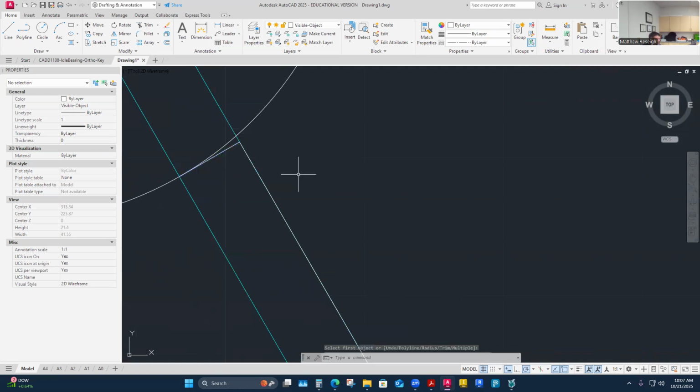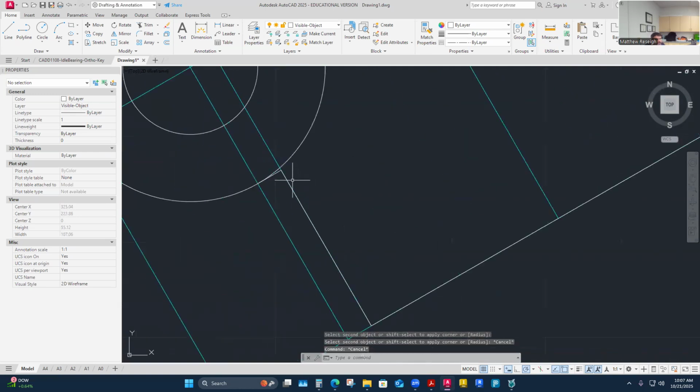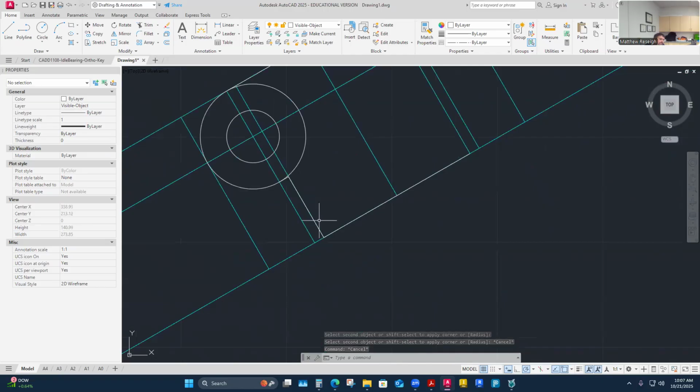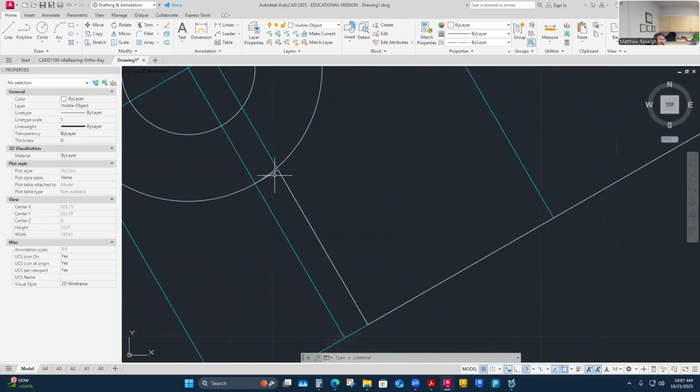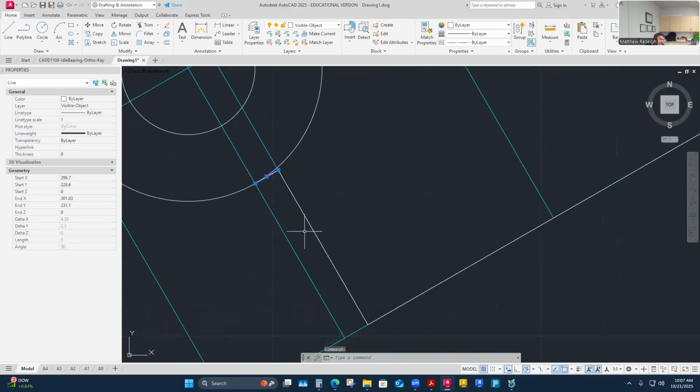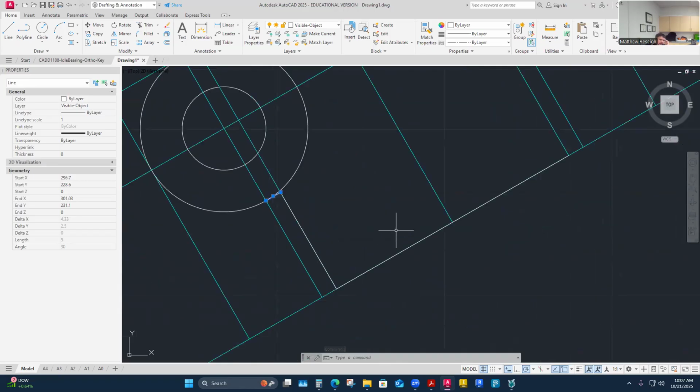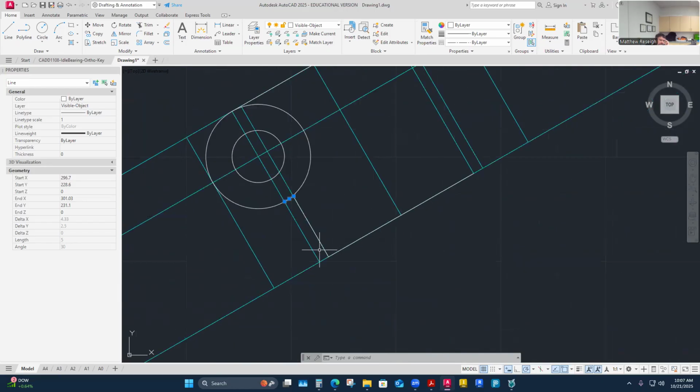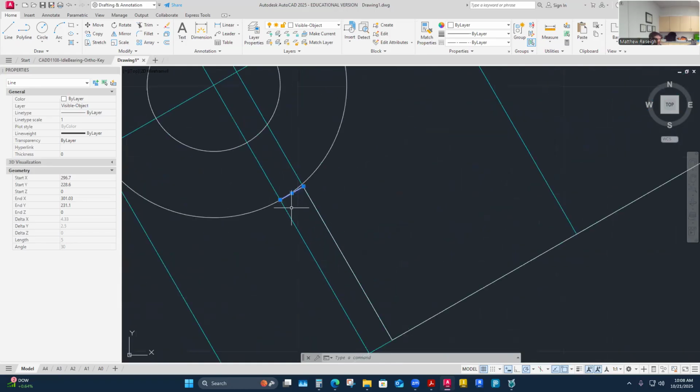And it won't let me do it because of the distance I have, which is what distance? Right here. It's only 5 millimeters. That's the difference of how wide the 80 millimeter plate is to the spacing, and it's 90 millimeters. It's 5 on each side. That's why I offset 45 and then 40. And then I might need to draw this in.